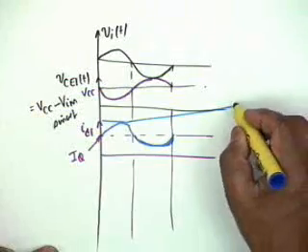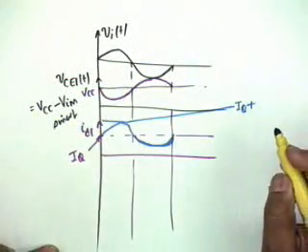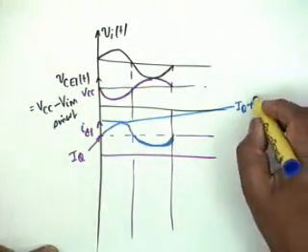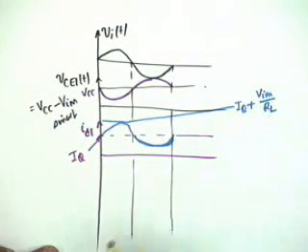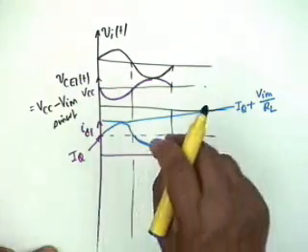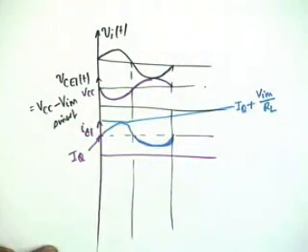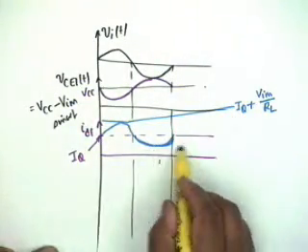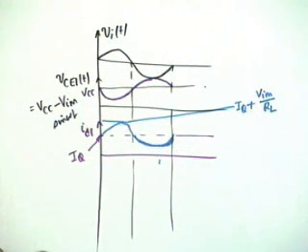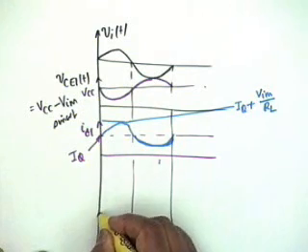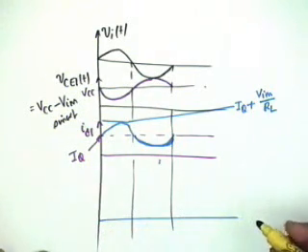IQ plus VIM divided by RL, agree? V0M is approximately equal to VIM, and the minimum value is IQ minus VIM by RL, alright. My drawings are not very good, but you should take this with a pinch of salt, okay.